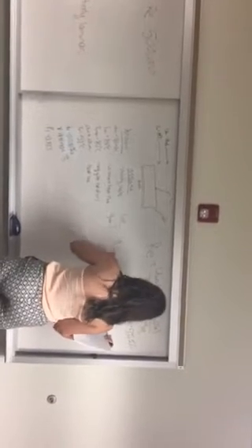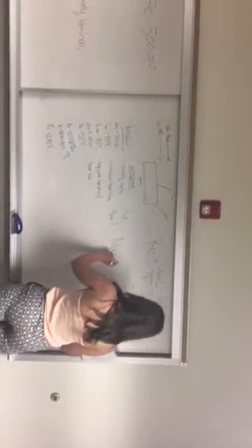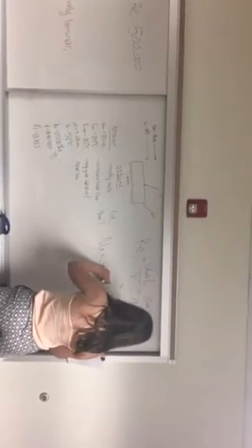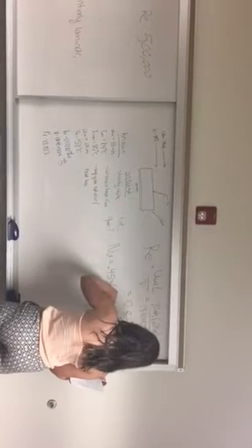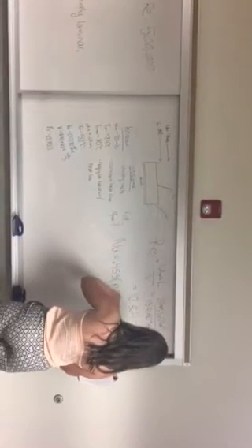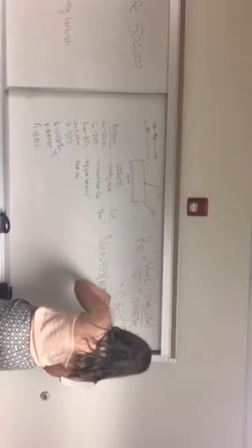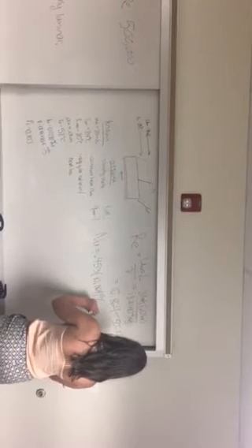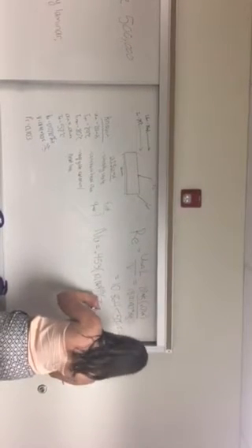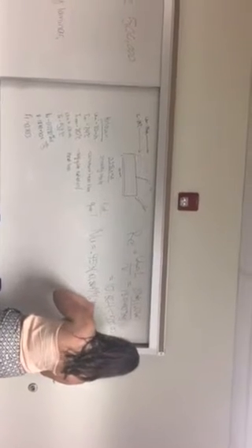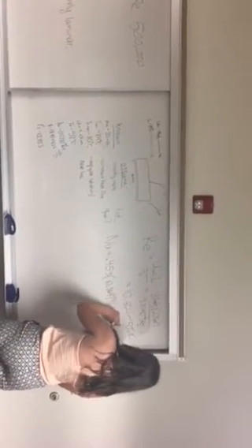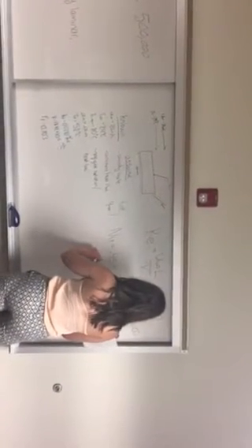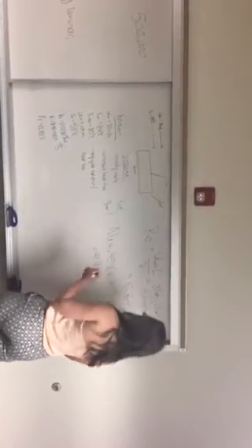We're going to use the equation Nu equals 0.453 times Reynolds number to the 1/2 times Prandtl number, 0.703, to the 1/3, and then Nusselt number will come out to be 41.90, unitless.